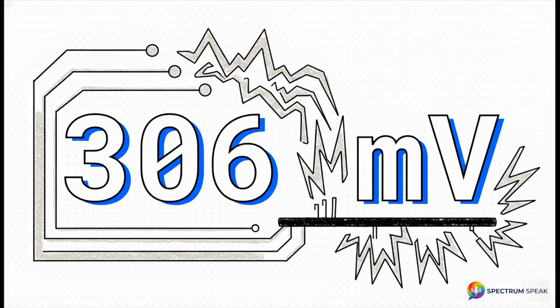When we add up those voltage drops, 103 millivolts plus 102.5 millivolts plus 100 millivolts, we get 305.5, or roughly 306 millivolts. Because of that shared daisy chain, you have literally just injected 306 millivolts of noise straight into the ground reference of your circuits. For a sensitive low-voltage analog component, a 300 millivolt swing on its ground pin is an absolute fatal blow. It's game over. This perfectly illustrates why the text clearly mandates that you should never, ever use this configuration between circuits operating at widely different current levels.